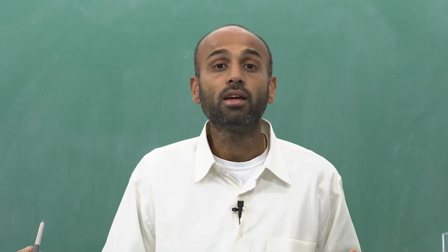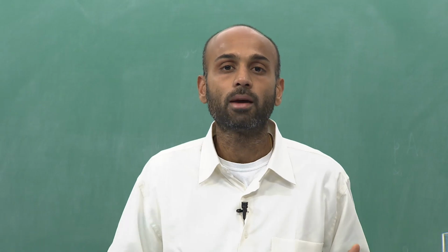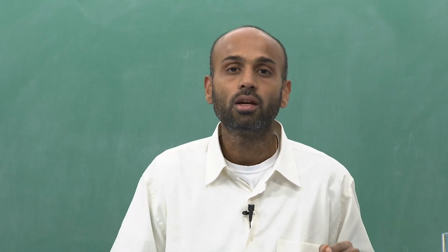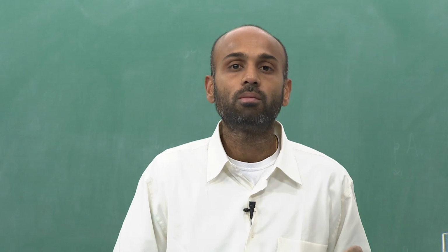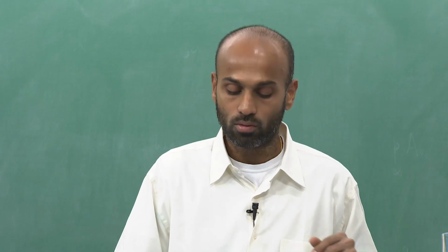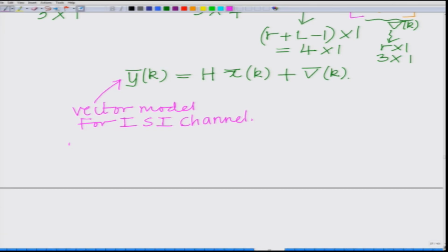Now, we are going to design the equalizer. Remember, we are designing a 3 tap equalizer, that is r equal to 3. So, let the taps of the equalizer be denoted by C0, C1, C2.